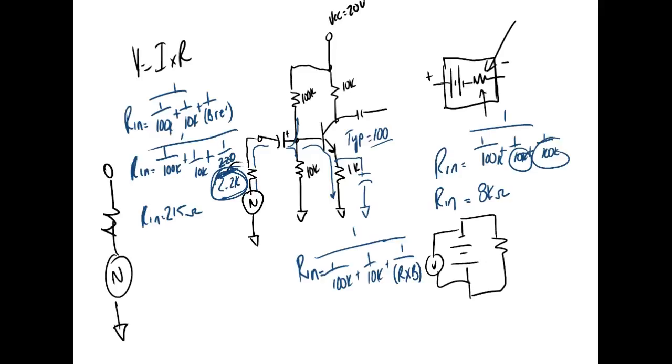The gains we can get out of this thing. Of course, all of them give us a power gain. Y'all understand? So when I talk about the gain of an amplifier, I'm talking about what gain do we get to get the power gain. So what two gains do we get out of this guy? We get a voltage gain and a current gain, and that's the characteristics of common emitter.